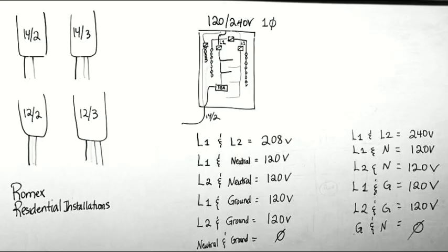Now, because I can put 169 lights, that doesn't mean that I'm gonna put 169 lights on that circuit. If I'm going into a house and I can put 160 lights into a house, I'm not gonna put one circuit for that house. I'm gonna put at least a minimum of 2, because if one of the circuits fails for any reason, I want the customers to at least have a little bit of light in the house, right? Some light.